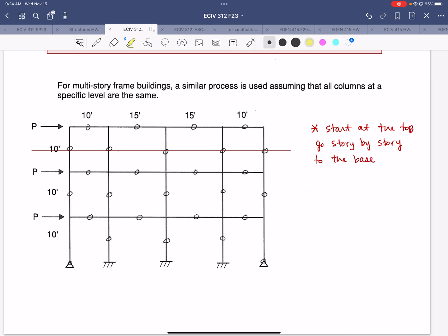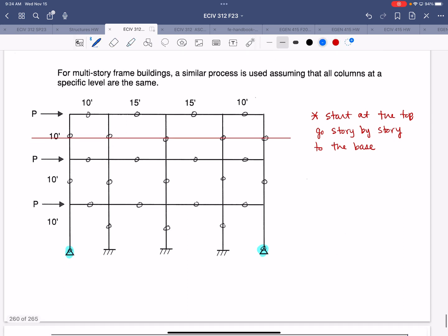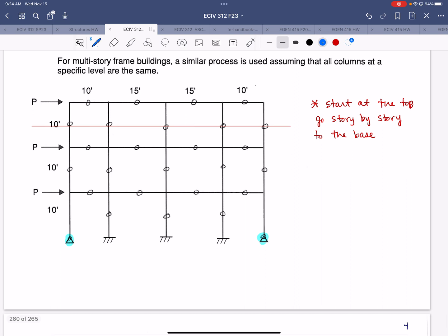And then down below, I'm going to note that if exterior columns are pinned, the hinge is at the base, so we don't add one at the midspan. Well, that's exterior specific to this frame, so I'm just going to write in general: columns that are pinned already have a hinge at the base.